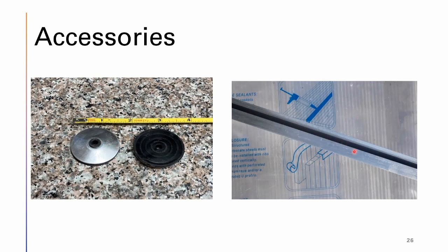This is your J channel. So if you look behind on this picture, there's open channels in your polycarbonate. You have to protect those. Otherwise, you'll have condensation and dust buildup over time. So you can use like HVAC aluminum tape. This H channel, this aluminum channel is another mechanism to do that. It's much more permanent, looks more professional.